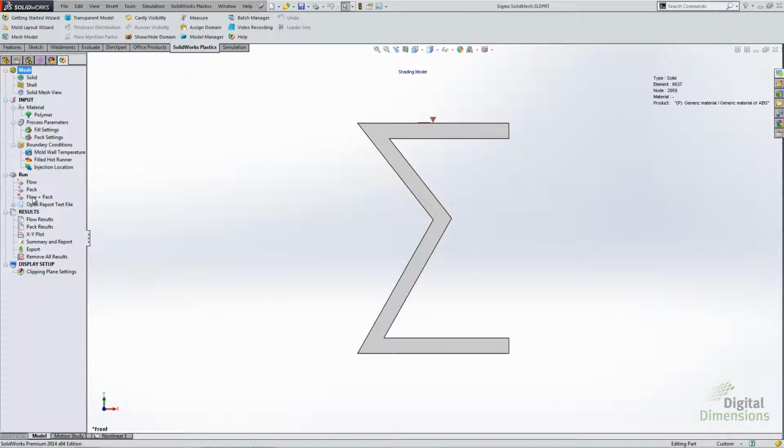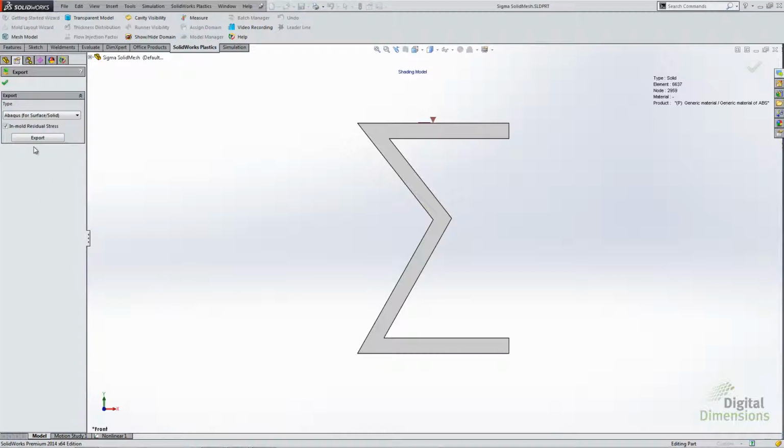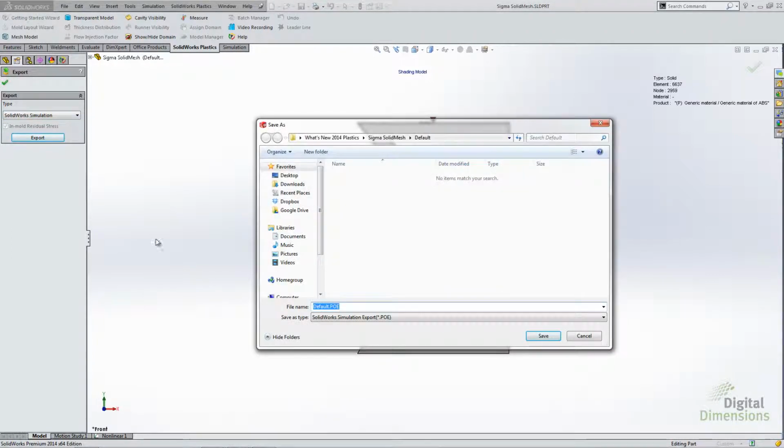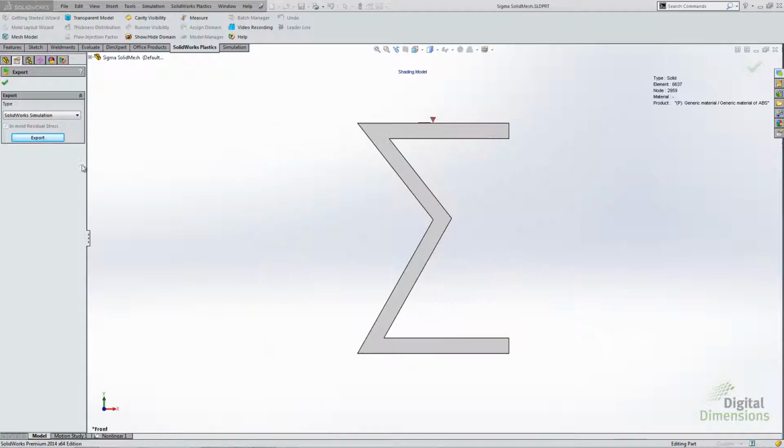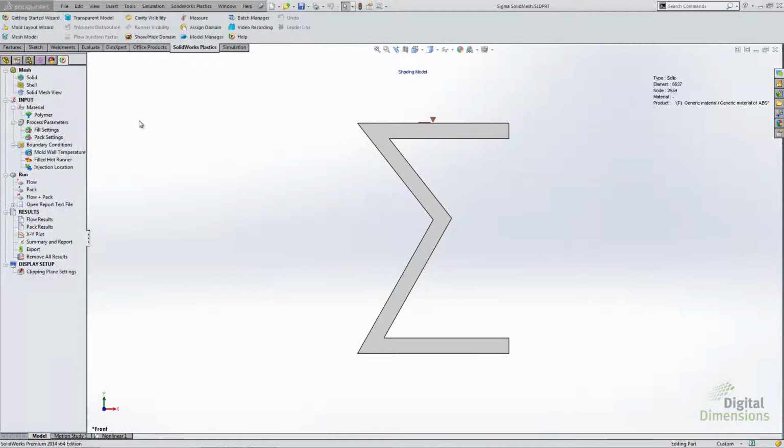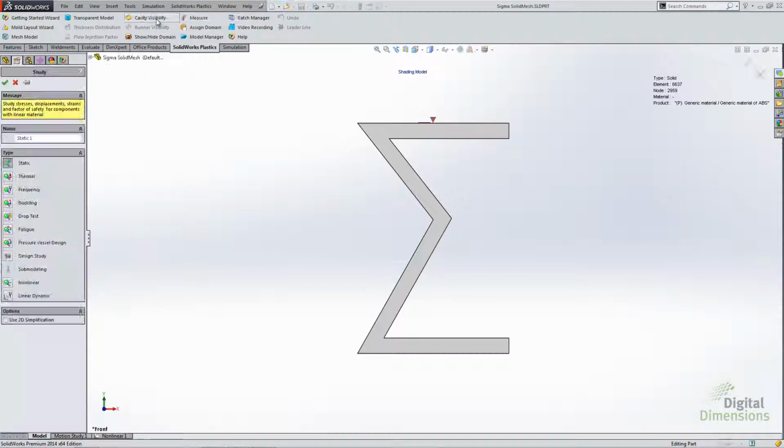Again, when all six requirements are properly done, you can now go in and right-click on the export folder, and under the type pull down, you should be able to choose SolidWorks Simulation and hit export. The file format you get is a .poe file. So once you've successfully exported your plastics results, now you can go in and import them using a nonlinear static study in SolidWorks Simulation.